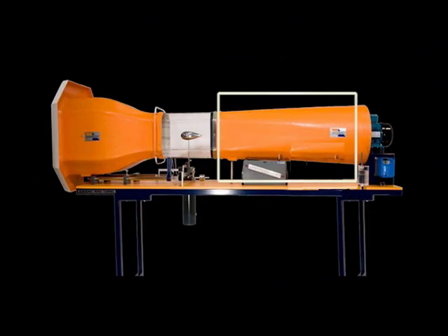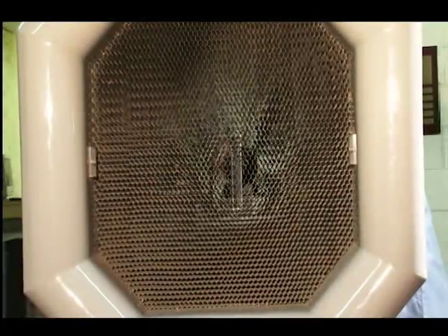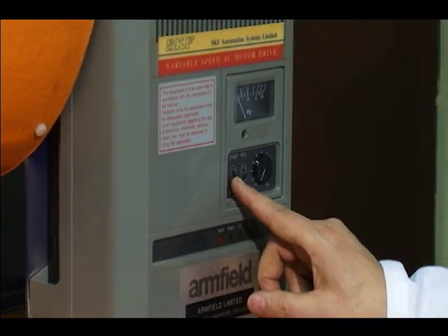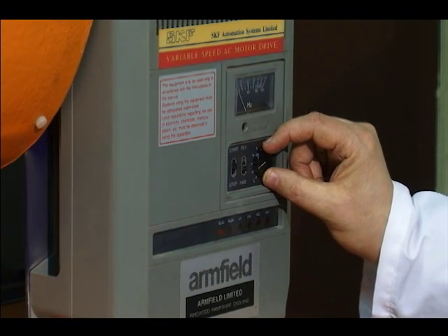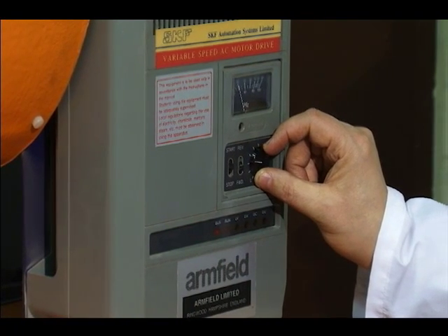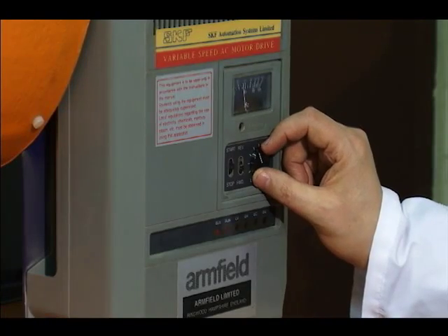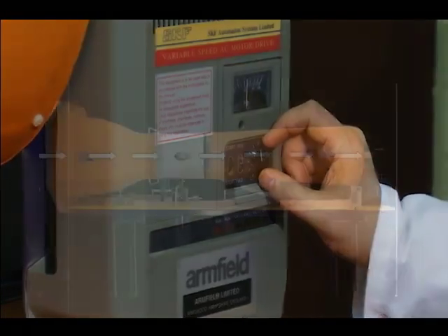A low-angle diffuser at the outlet end contributes to flow stability in the test section. It also increases air volume in order to reduce the airspeed as it exits the tunnel. A 5-bladed fan driven by an AC motor is located at the outlet of the diffuser section. The motor speed control unit allows smooth control of airspeed.